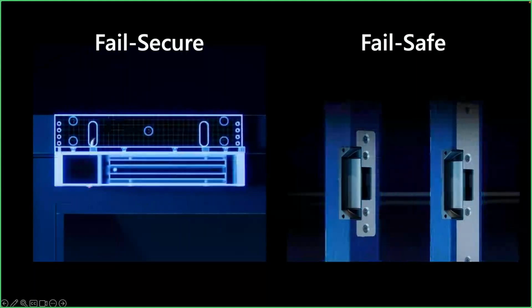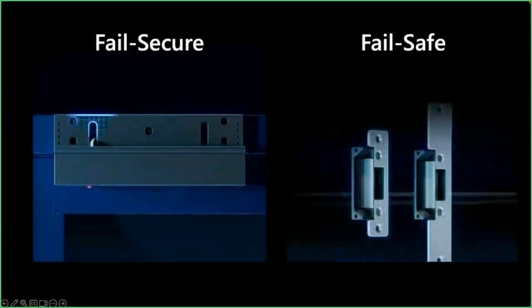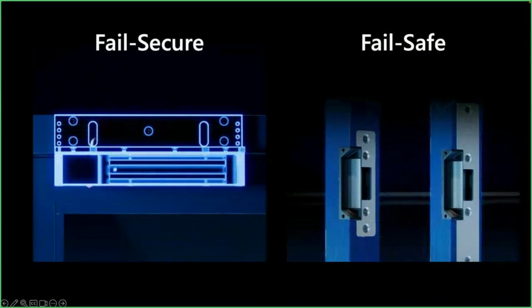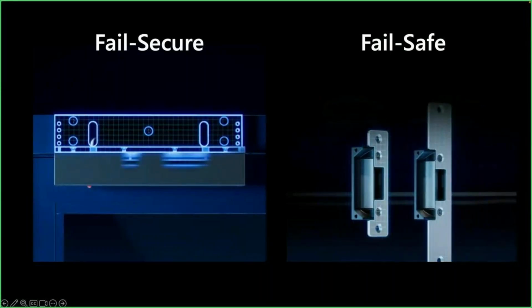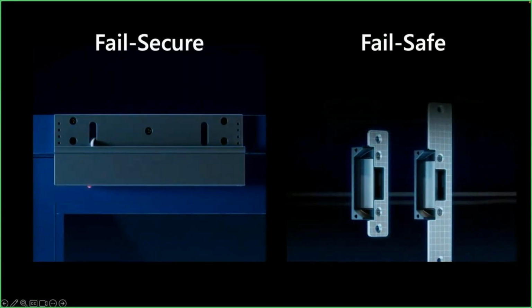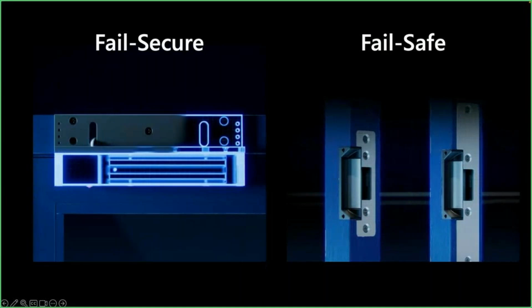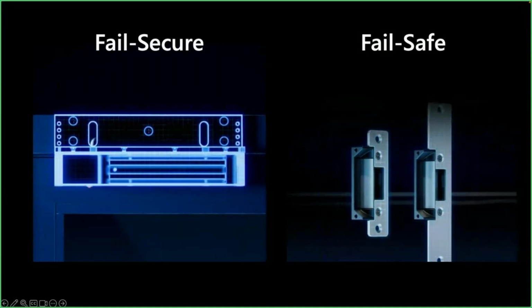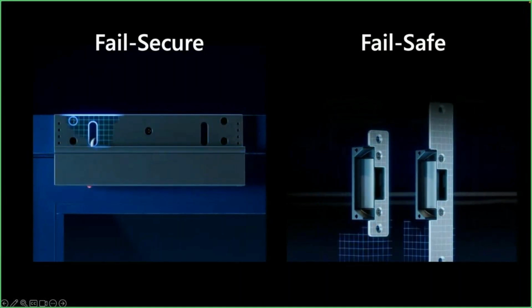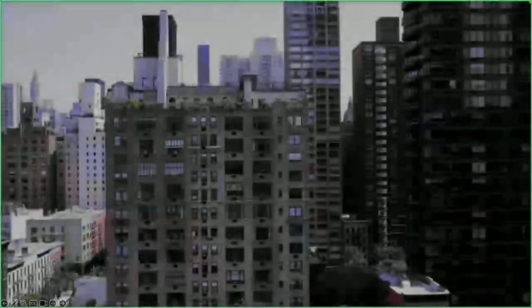So this is still how you want to connect this. Do you want to set up fail safe or fail secure? So basically, if the power goes out, what do you want to have happen? Does the door need to remain open, or does the door need to be closed, what needs to happen with that door. Your maglock choice or your lock choice typically determines this, so it's an important thing to think of.